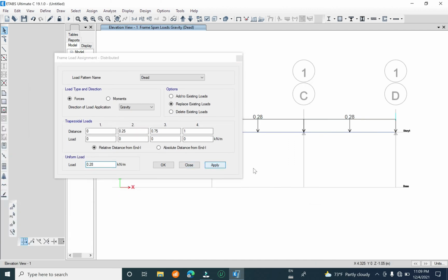Now we have to apply, and for the line load on roofs, for the Eurocode is equal to 60 kg per square meter, equal to 0.6 multiply with 0.7, the width or the base of the rafter, and we have to apply. Because we did not just select, we have to select it again. Press Ctrl G, the previous select, and apply.